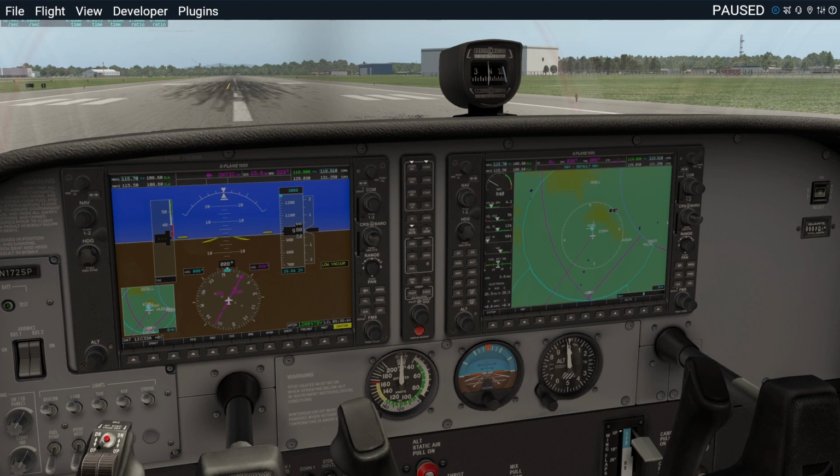The airspeed indicator also shows true airspeed at the bottom of the screen, and it incorporates the outside air temperature. The way it does this is it uses an air data computer to take data readings from the pitot tube and the static port, and also an air temperature probe, and it calculates the true airspeed, which is displayed at the bottom of the airspeed bar.